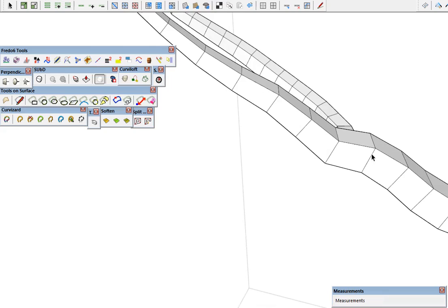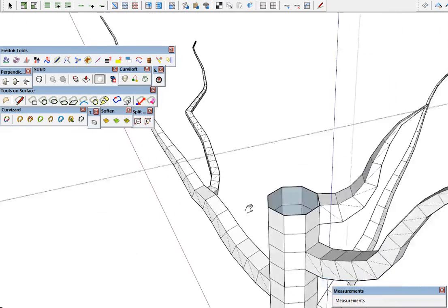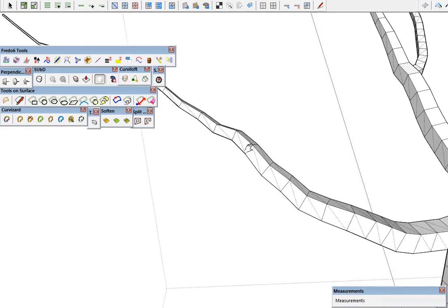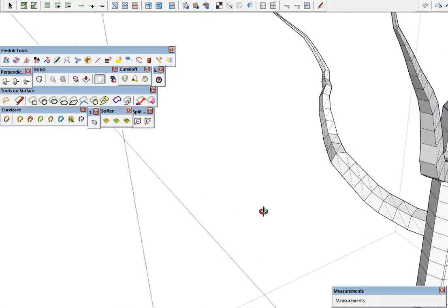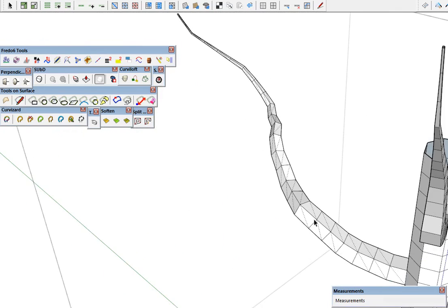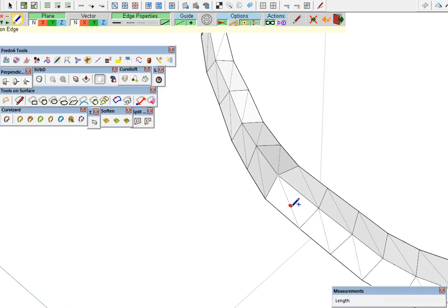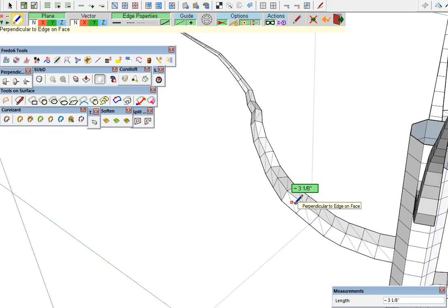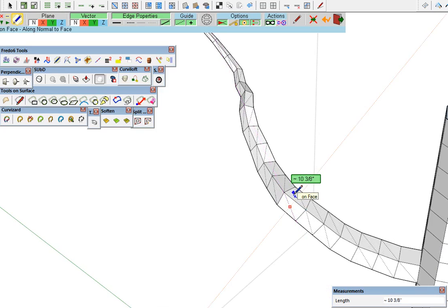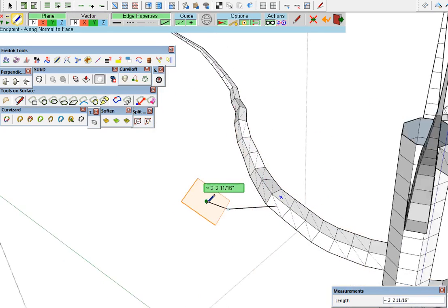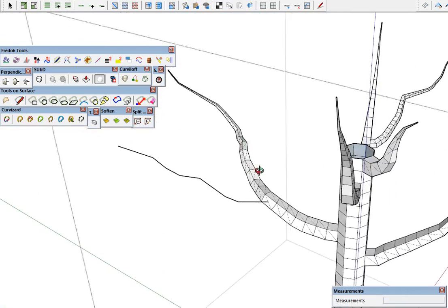So the other thing I was saying, because these aren't coplanar here, these edges, if we wanted to get in and draw one, we didn't have Artisan or Vertex tools to make that planar. We could get in here. Let's just use draw along, turn on hidden geometry, and just kind of grab the center here, the midpoint of that triangulated edge. And let's get in here. There we go. And let's draw up here in this direction. Something like that.